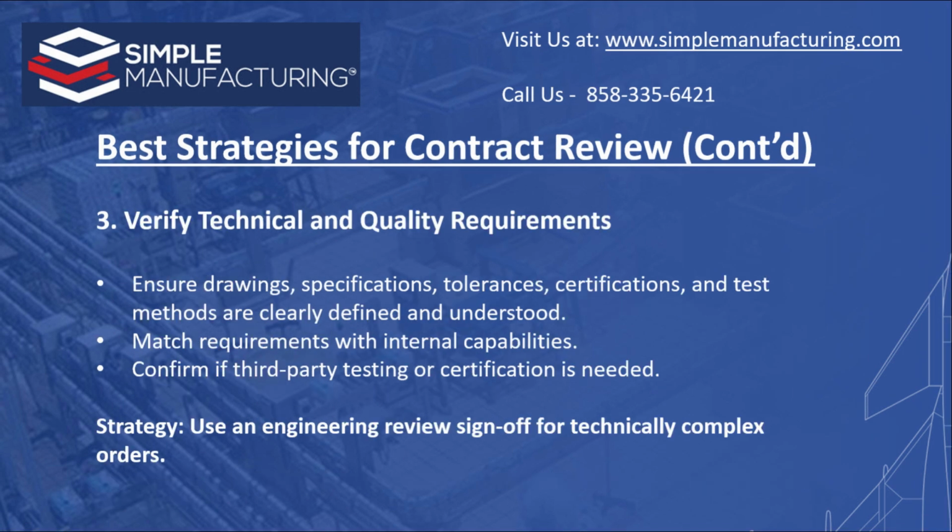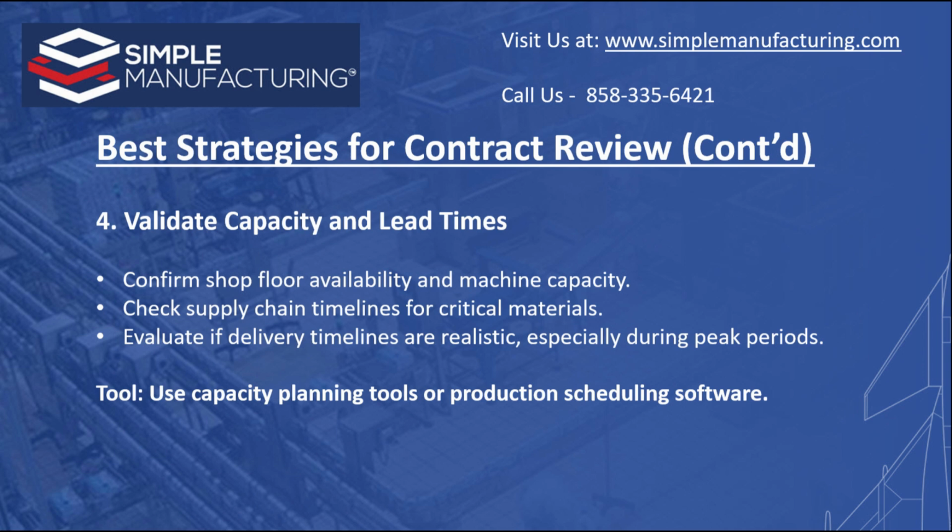Third, verify technical and quality requirements. Ensure drawings, specifications, tolerances, certifications, and test methods are clearly defined and understood. Match requirements with internal capabilities and confirm if third-party testing or certification is needed. Fourth, validate capacity and lead times. Confirm shop floor availability and machine capacity. Check supply chain timelines for critical materials. Evaluate if delivery timelines are realistic, especially during peak periods.